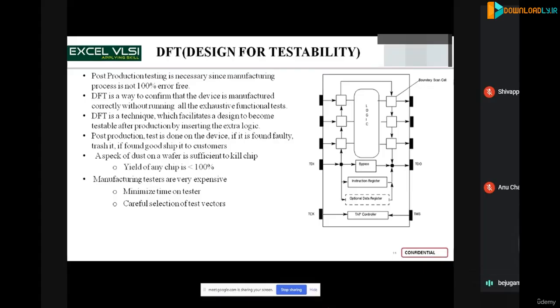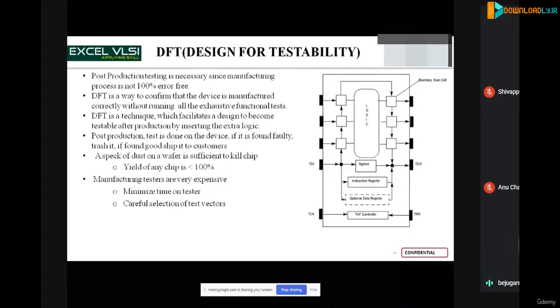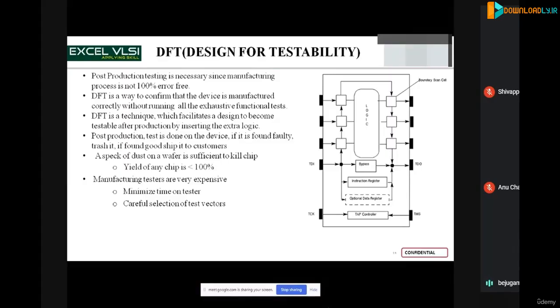At the design for testability stage, we send some scan cells or some test logic as input to the netlist, and we test the functionality of the cells at each and every node to node point and point to point of simple and complex cells, so that the vectors we give at each input of the gates are tested properly, and we get a finalized output, which is the output we are expecting.